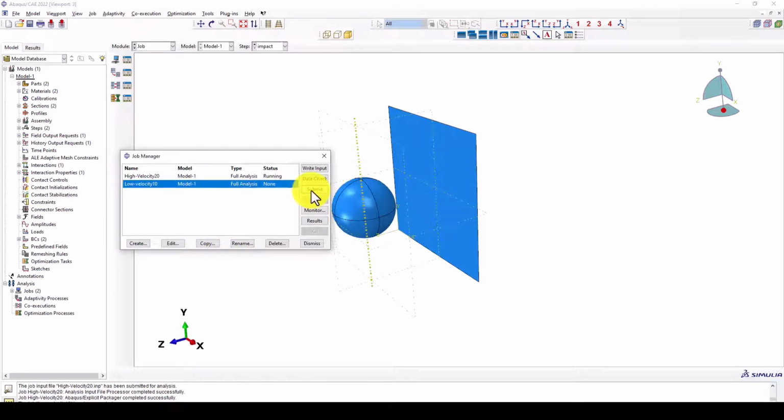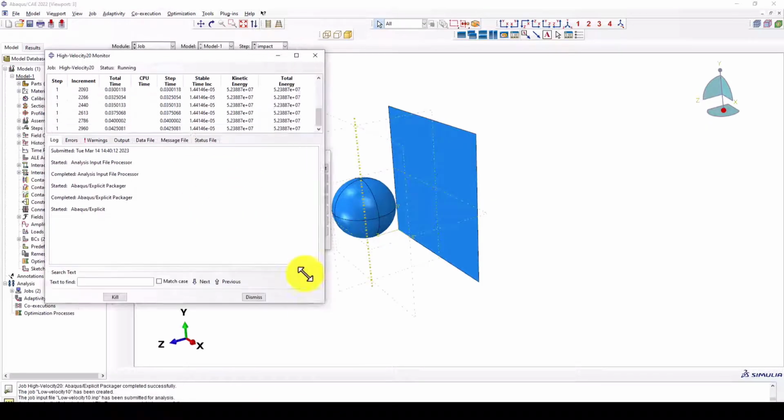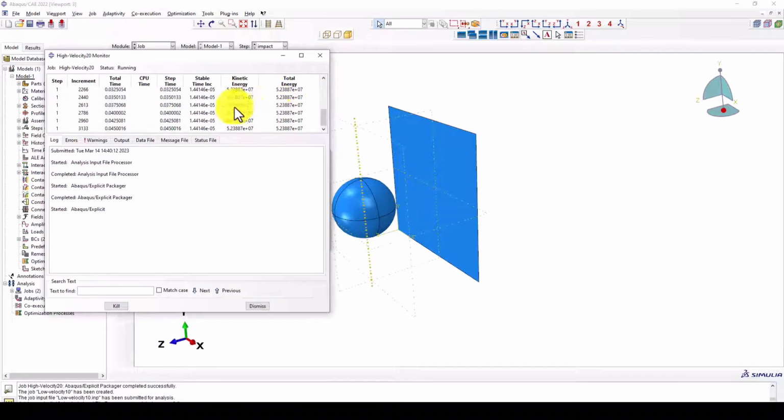Now we are defining the strain rate dependence. This helps us also include the angular deformation between two originally perpendicular lines, and the formula of volumetric strain, that is delta V by V. Delta V is the change in the volume, and V is the original volume.